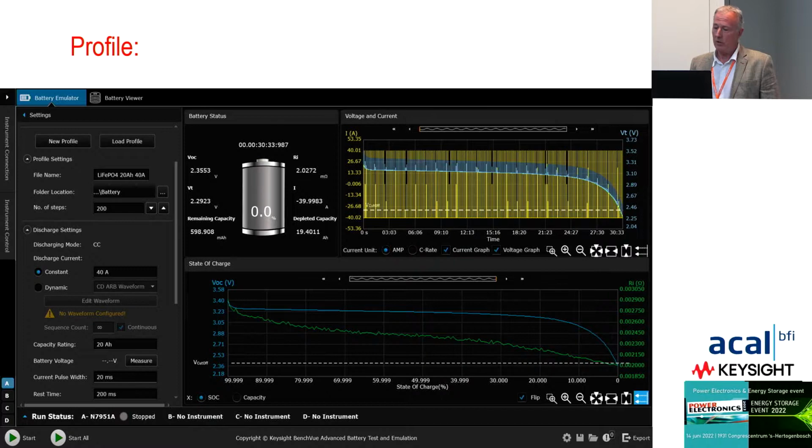So all of these three features play against each other: state of charge, available voltage, and the internal resistance. And the nature of the device's current drain on the battery can also have significant impacts. I think the ideal profile for a battery is if you just take a constant current, it will give you the longest possible life before the battery reaches the cutoff point and is unable to continue providing energy to your device. With dynamic currents, every time you take a high current pulse, the voltage will drop and then not recover back to its previous state. So your runtime will be curtailed.